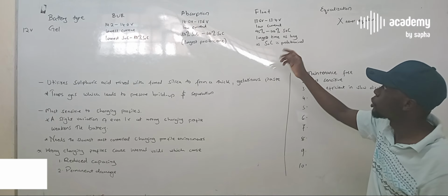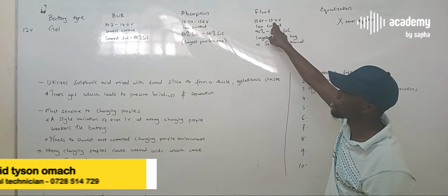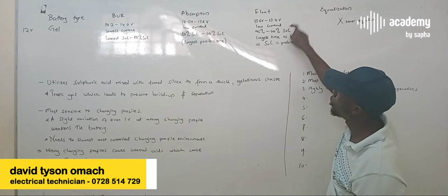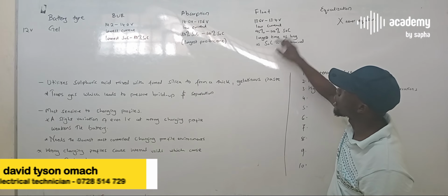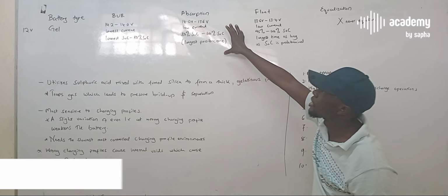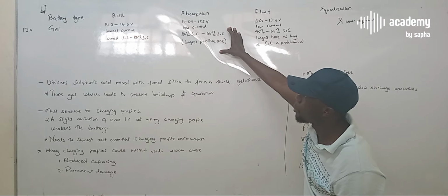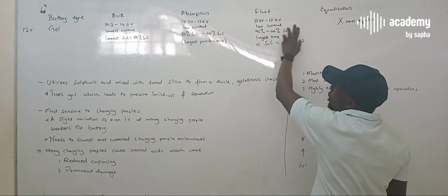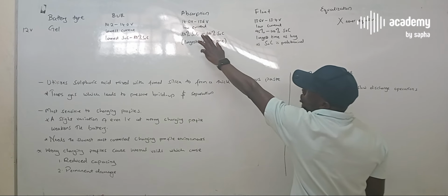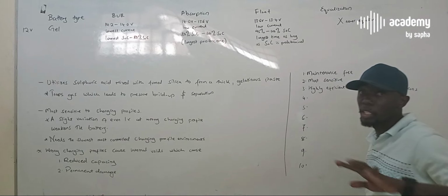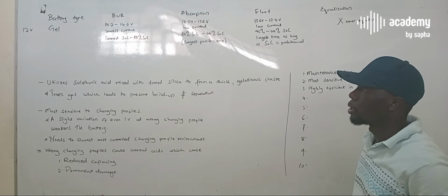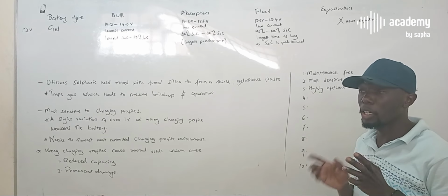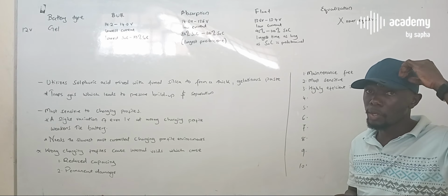But for those who are taking you to the float stage, they're saying you lower the voltage again by 0.2, low current, and keep it here. So it's either at absorption stage or a float stage. So a gel battery should be maintained between 13.4 to 14 volts at any given time. Now that is after you've understood how to know the SOC of your system.